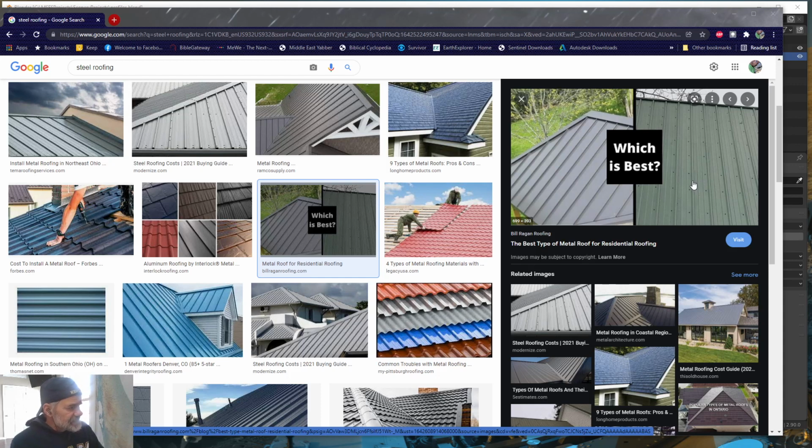The only difference is the distance between the main ribs is 9 inches. Okay, and then in between the 9 inches, you have a minor rib. The major rib usually stands about 1 inch tall, and it's usually about 2 inches wide, and it has a kind of a plateau type of profile. You got 2 sloping sides and then a flat top. Okay, and the minor ribs are the same thing, except they're really shallow. They're only about 1/4 inch tall, but they look the same. So, and then you have to model the fasteners. You have to put a little dot in your model.